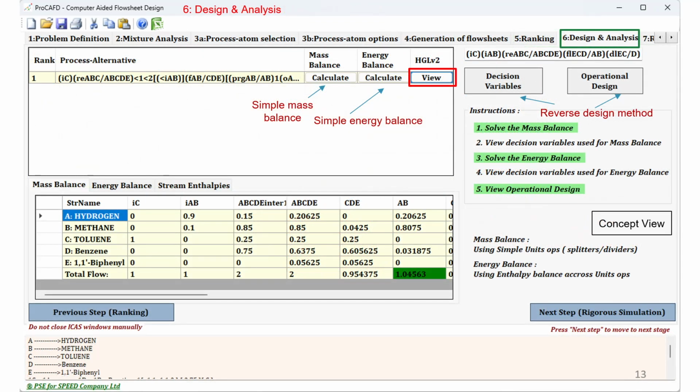This step involves the transition from the synthesized flowsheet to the design of the operations in the flowsheet. In order to perform mass balance, simple models, surrogates of the rigorous models, are used. Each operation model requires a set of model parameters. These are included in the knowledge representation at level 2 as input data. Using the input data, process simulation is performed with simple models. These results are added to the level 2 as output data.